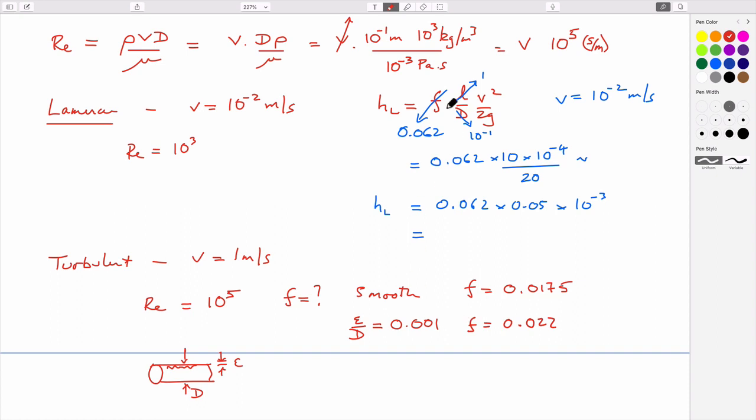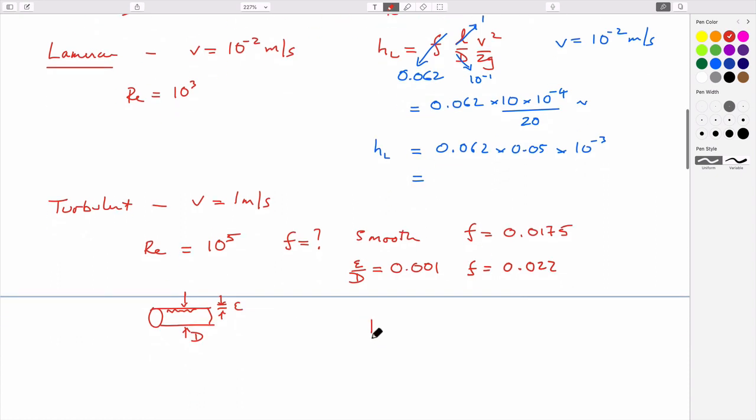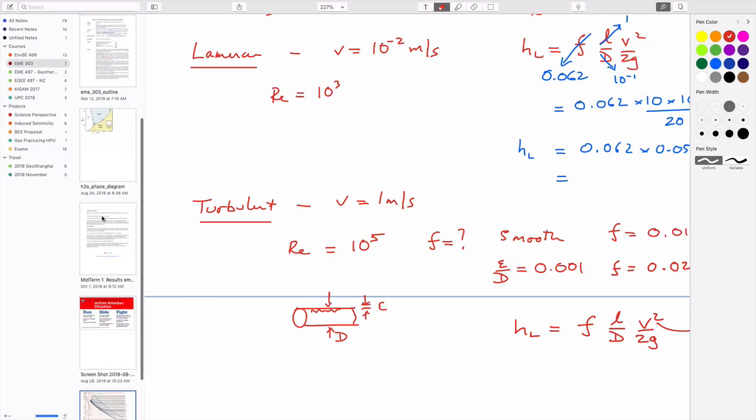Which means if you calculate the head loss from either one of these, just directly by using the friction factor, length of the pipe, diameter of the pipe, and the velocity in the pipe which we have defined, which is now a larger number, we can calculate what the head loss would be in the system. So it's no different from that. So this type 1 behavior is the easiest. So going back to our chart maybe that we wrote down before.